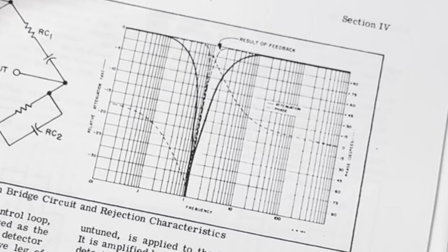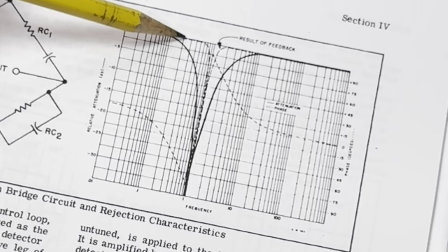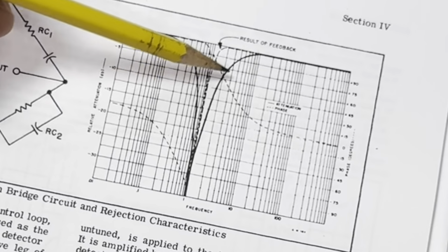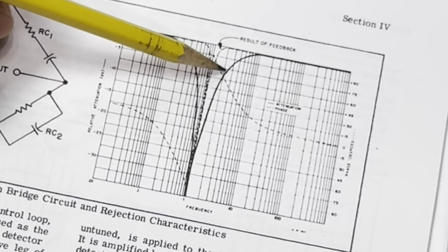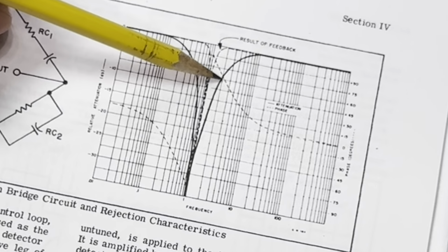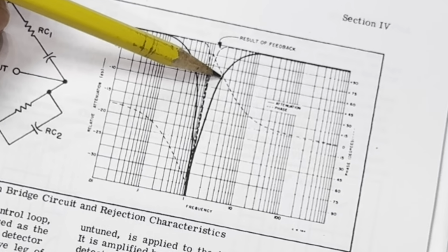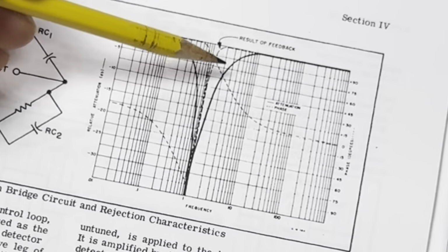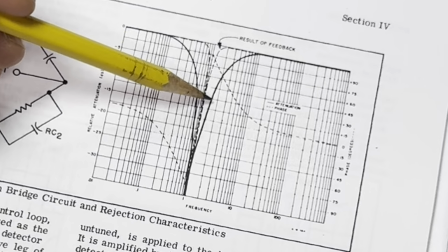Well, this isn't good because if we have some second harmonic content produced by our device under test, that second harmonic content is going to be attenuated, and it's not going to be counted correctly when we go to make our distortion measurement. So therefore, our distortion measurement's not going to reflect the actual distortion levels, because the distortion products that we're measuring, the second and third and fourth and so on harmonics, are going to be attenuated.